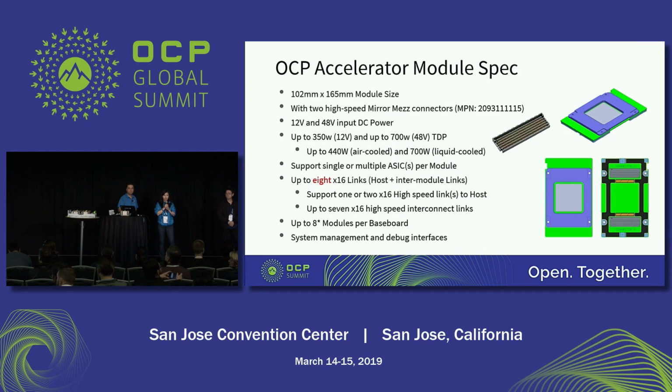This is a high-level spec. Yesterday we officially contributed the design spec to the OCP community, so you can all download it. We have a 3D file, heat-sink design examples, design files, and also the detailed pin mapping spec, all contributed to OCP already. Just some highlights here. The size is 1.2 by 165 millimeter, and then we have a heat-sink design. We designed this sample for a Facebook project, and we enabled one of the projects from yesterday's keynote.